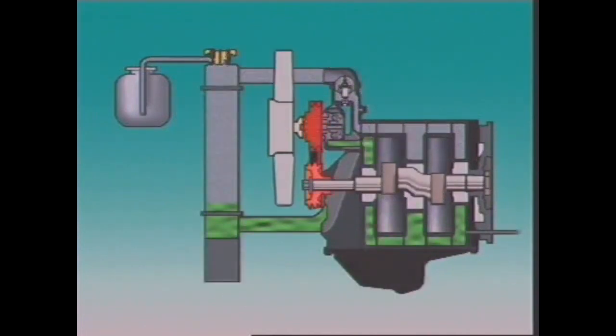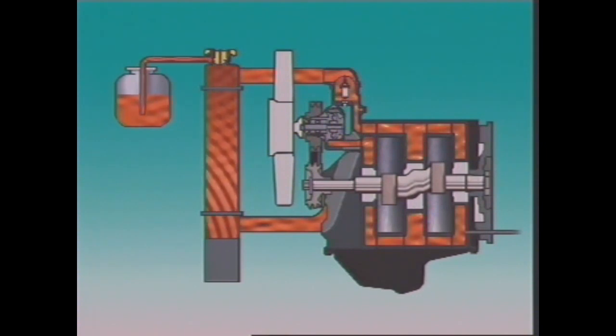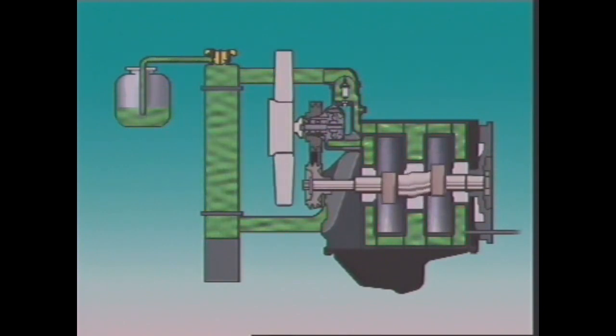A pulley on the end of the eccentric shaft drives the water pump and fan. In the rear housing, the coolant reverses direction and returns to the front of the engine. It passes a thermostat. As in a piston engine, it is closed when the engine is cold, but opens as it warms up. The rotary engine has an overflow system much like that of a piston engine. As pressure builds up, coolant expands into an overflow tank. As it cools, pressure drops and it returns to the radiator. A viscous hub links fan speed with engine temperature.